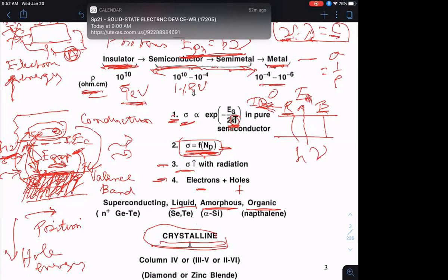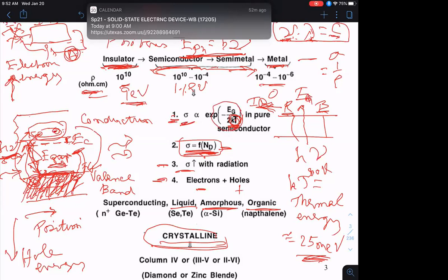That energy separation is so small compared to the thermal energy, which is called kT. This quantity kT, by the way, is known as the thermal energy of the electrons, okay? And at room temperature, 300 Kelvin, this quantity is 25 milli electron volts, approximately, okay? The band gap is 1 electron volt. So the thermal energy is 25 milli electron volts, which is much smaller than the band gap. That's why if you plug in these numbers, you don't really excite a lot of carriers, but you do excite some.